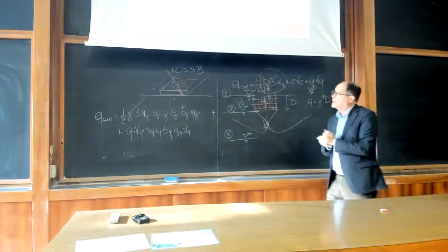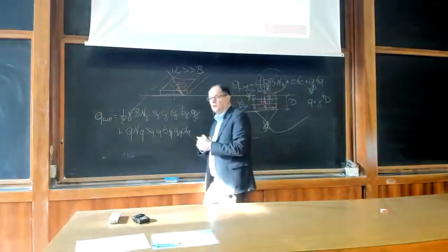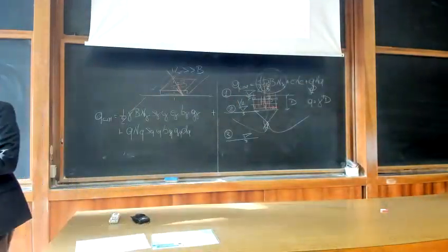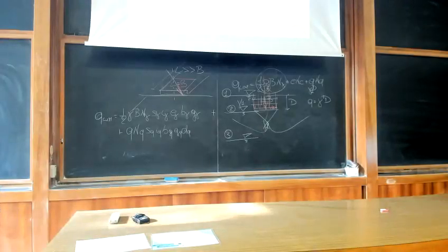And I have reported here just an example of shape factors, depth factors, load inclination factors provided by the various authors. And once again, different authors recommend different expressions, and you have to decide which one is the most suitable. For example, you see shape factors, Meyerhof suggests these values SQ and S gamma as a function of B over L, which is the geometrical ratio, and phi.